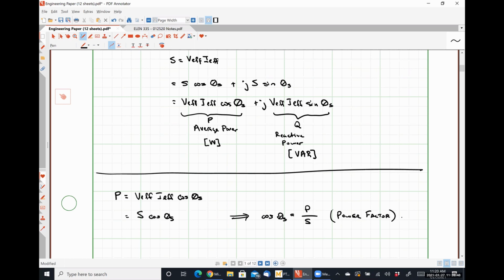But they have to, so they have to spend money to generate this power for it to just get sent back to them. So they're effectively burning coal or putting wear on their hydroelectric turbines or however they're generating their power for no real specific use, and so they'll penalize you for it. So power factor correction is a means by which to fix a couple of things.